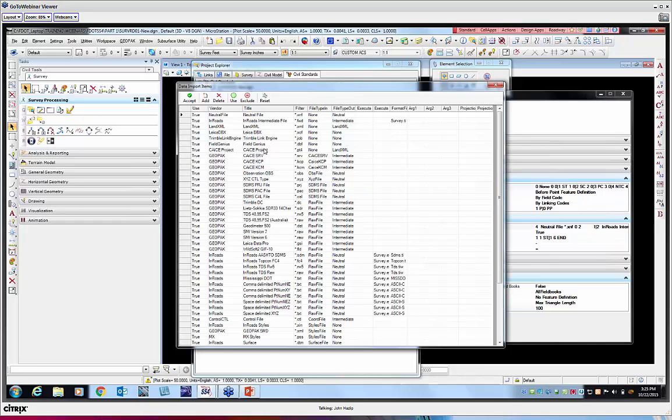In upcoming webinars, I'll show you how to import a KCPT4 and also XYZ files and control files. Bentley Survey can also process data, so a control file, a CTL, can be brought in, and then an OBS can be brought in and read, and data processed using geographic coordinates or geographic projections.